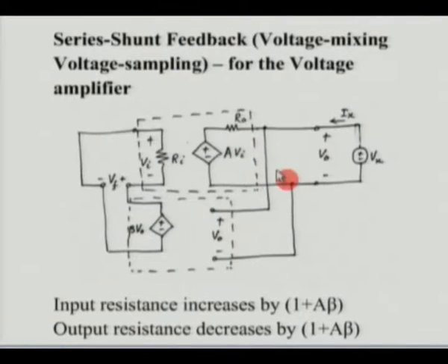Now if you substitute it, you would see that these numbers drastically change. Depending on the beta you have there, the input resistance can jump from 1 megohm to maybe, at least theoretically, 100 megohm. You may not get that, because getting 100 megohm in a circuit is very difficult because of leakage resistance on your PCB. You can never get that on a microboard because of the leakage currents, but at least theoretically you have a possibility. Therefore you would see that in very precision applications, this is why amplifiers are soldered and printed circuit boards are made to avoid leakage currents.